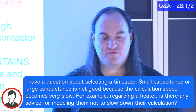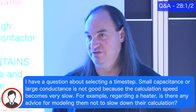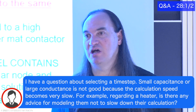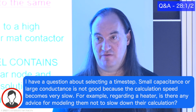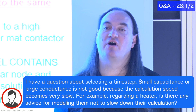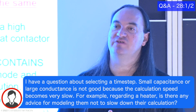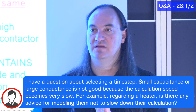Well, so it's different. The time step doesn't really affect the heaters so much. The heaters will affect convergence. So convergence is how much I'll allow a change since the last time I tried to solve. Time steps are how far do I advance in time in a transient solution in order to get to the end.